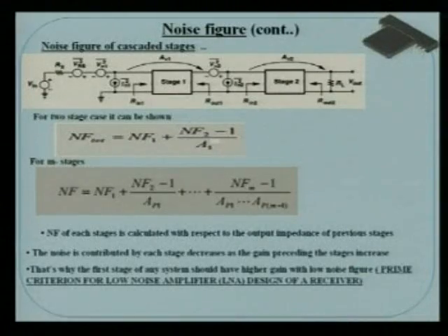So the overall noise figure is 6 or 7 dB, and it has various components called functional modules in the system. Between my antenna and the output, across the whole RF block, I have to estimate that noise and that gain to find out my overall gain.